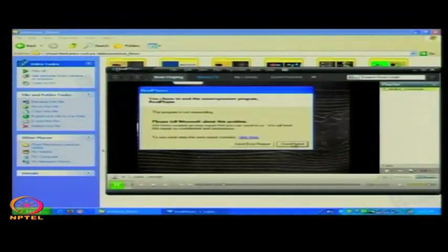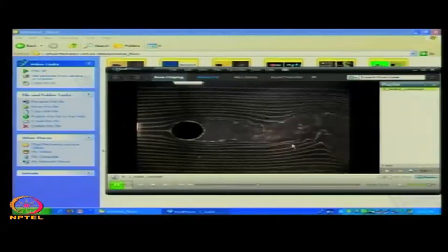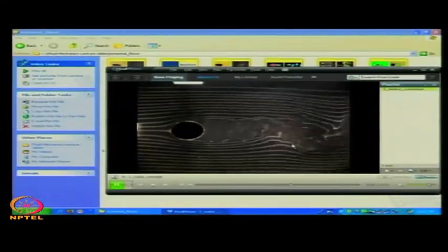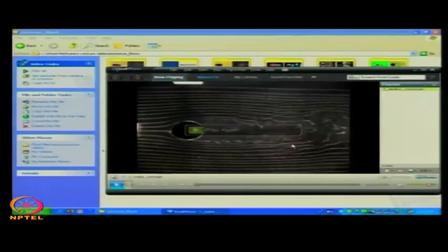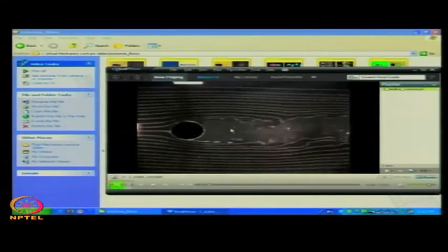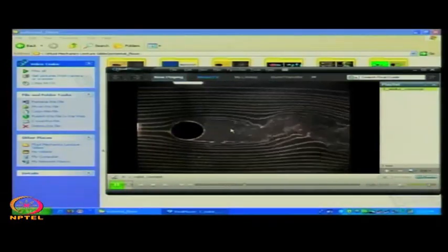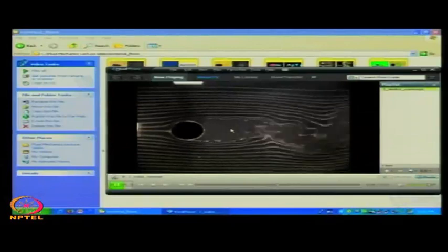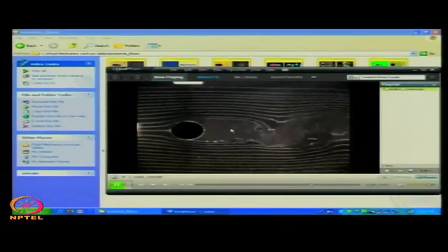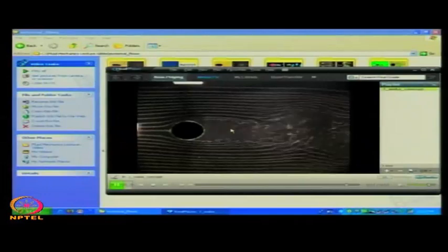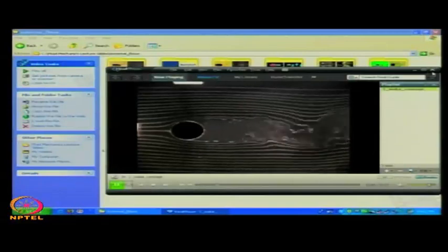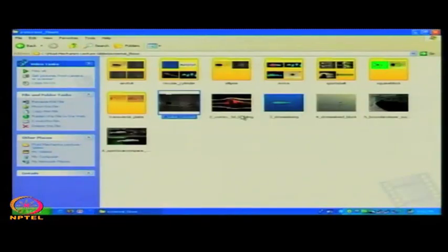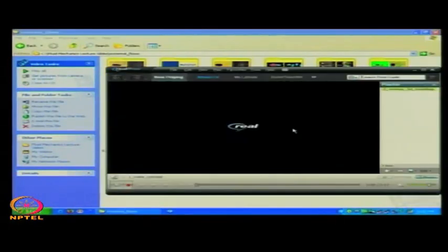So, if you look into this flow, this is flow past a cylinder, okay. If you consider that circular thing as a cylinder where the length is perpendicular to the plane of the figure, if you play it once more, you see that the separation has occurred somewhere maybe in the middle section. Beyond that, you have the region in the back where you have these rotating structures, those are low pressure regions. But if you consider a different shaped body, you may also see a very similar thing.